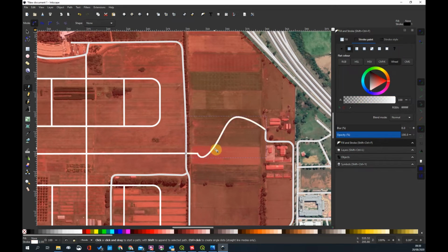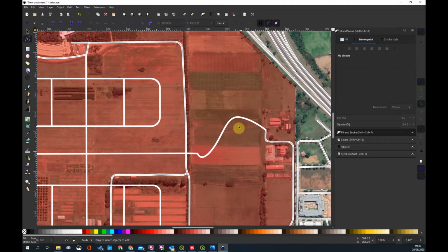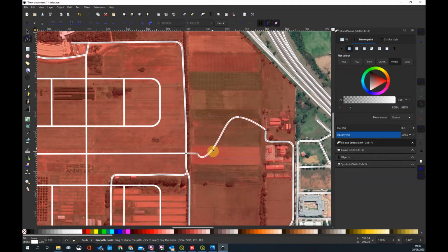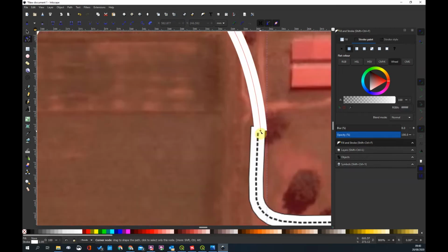Okay. Now I'm going to go back and I'm going to edit that curve. I want it to work a lot better. So this point I'm going to pull up to there. And you can see now, and what's neat is you can click on these nodes and you can convert these nodes from round to, so you can make them work like arcs, for example. So here you can really go to town and make, and it's a quick way to kind of sketch and kind of get roads to do what you want. So here you can see I can make quite an interesting shape.